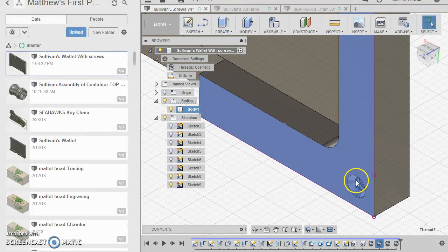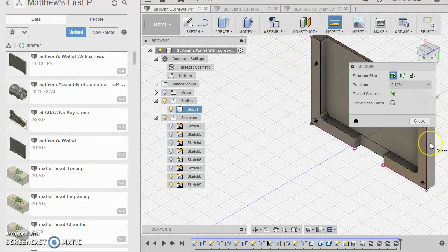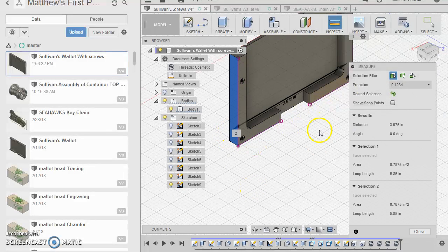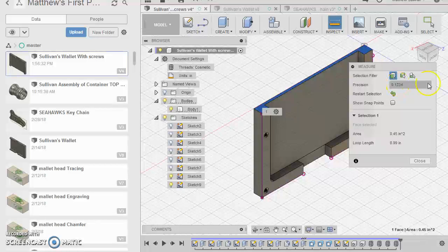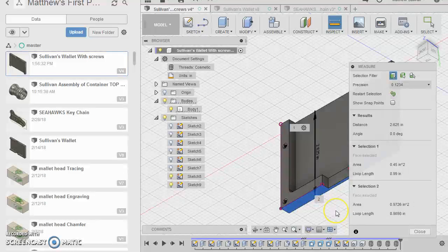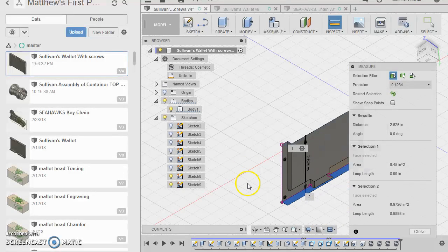So you can see we have threaded holes with a countersink, and I'm just going to show you two more features that I think are critical. This face to this face. If you're going to hold uniformity, make the overall part 3.975, and reselect from this top face down to the bottom, and the overall length 2.625 at a maximum. In overall length, I think you're going to be really happy with the product you end up with for these overall sizes.